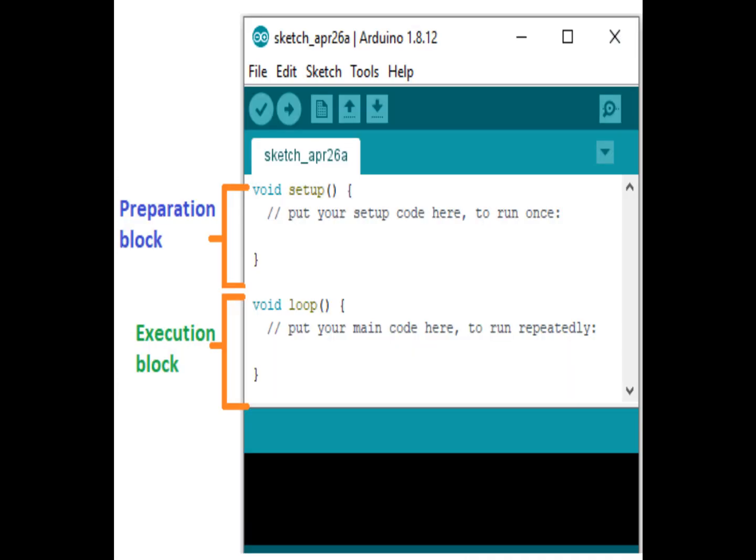When a code segment's execution starts, the setup function is called. Use it to initialize variables, pin modes, libraries, etc. The setup function will only run once after each power-up or reset of the Arduino board. It handles the prerequisites and sets everything up for the main functionality of the program to occur. Any code that lives inside the setup function's curly brackets runs once at the very beginning of your program and then never again. At least not until you reset the Arduino or upload new code.